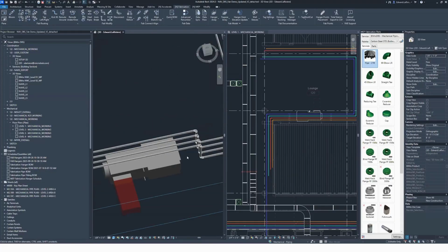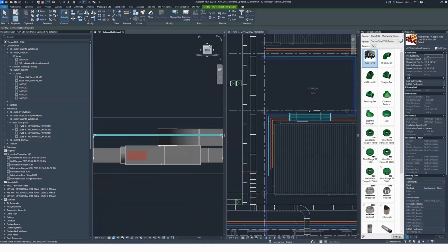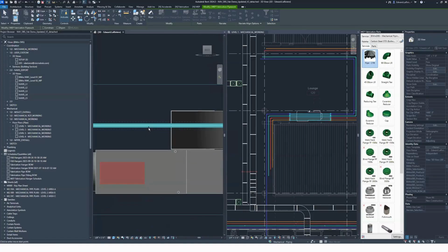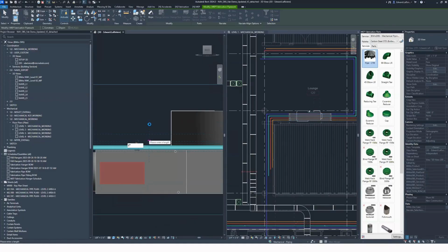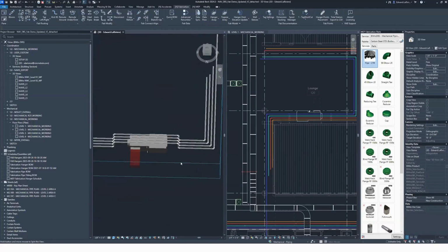And again, I really want to harp home how cool these 3D views are. If you need to get more specific, zoom right into those side views. You can start using those move commands all over again to line those guys up and then lift it so it's exactly 2 inches right off the top of that. Trying to make life nice and easy no matter what.